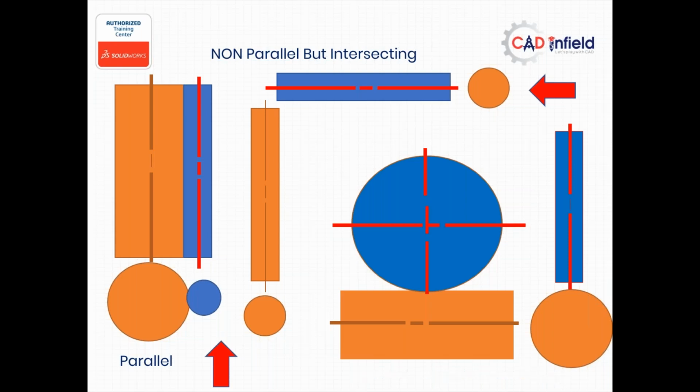We have discussed the types of gear. Once you know what parallel, intersecting and non-intersecting mean, then the question comes to mind whether I have sufficient distance, where I can use a gear or gear train, or with the help of an idler gear accommodate the sufficient length. If the length is larger, we have to go for the next type, which is either belt or chain, depending upon the application.